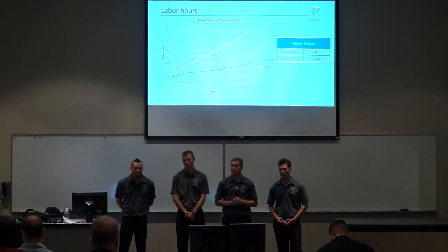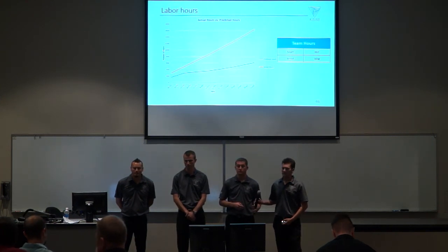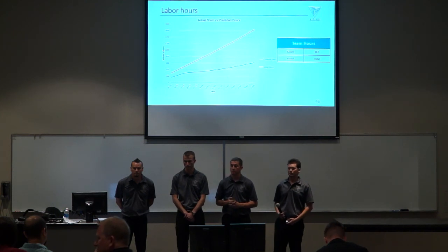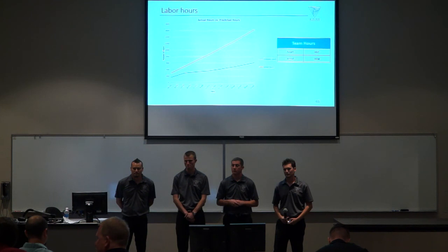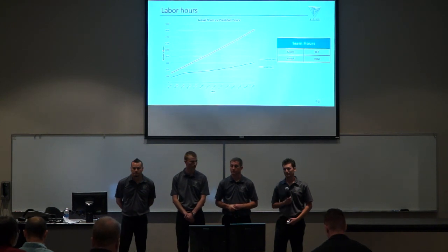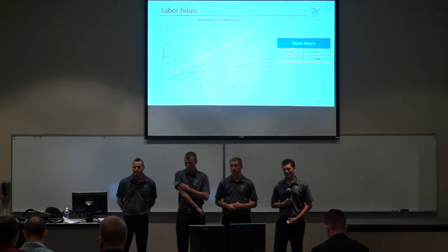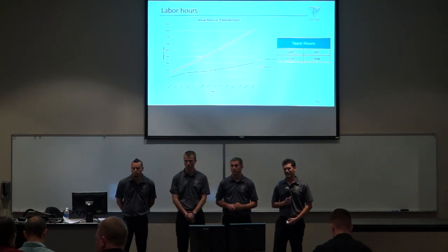Last thing is you got tremendous shaft horsepower on that 454, so maybe this was your supercharger recommendation, maybe for another team in the future to utilize some of that shaft horsepower to turn something else to produce, I think, a higher pressure air source. I think that would be an interesting follow-on for another team. Because like you said, you were running it unloaded. They don't really like to do that, and it seemed like you just weren't getting enough airflow through there.